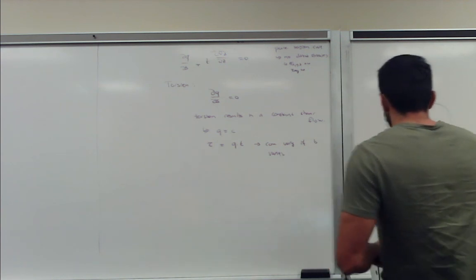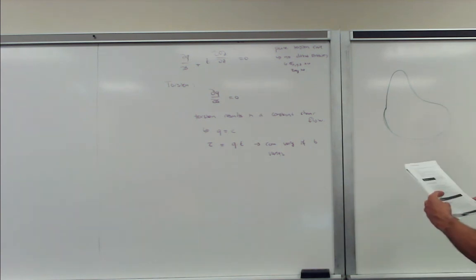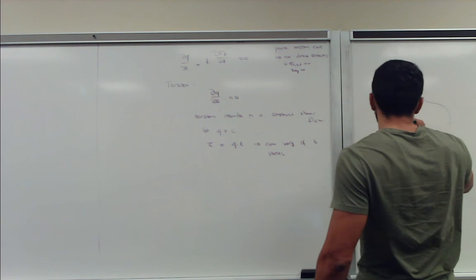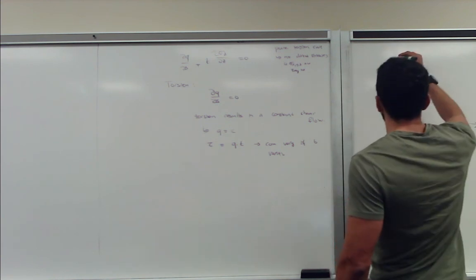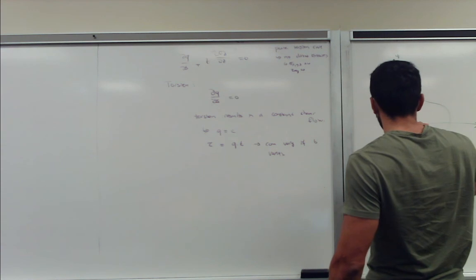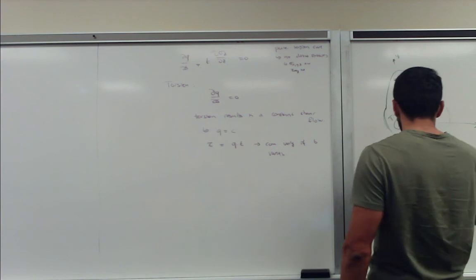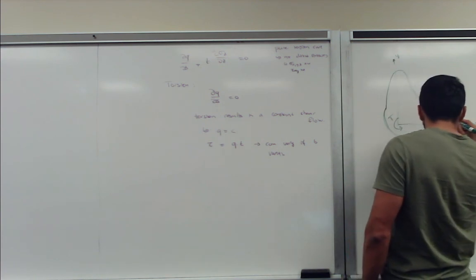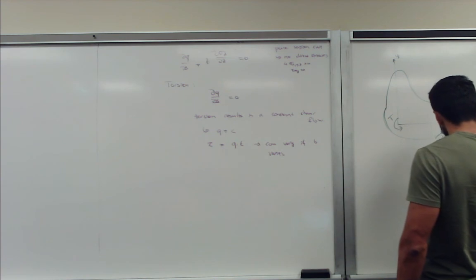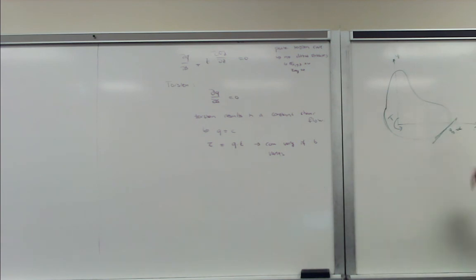Okay. So we have our x-axis and y-axis, x, y. Torsion is applied somewhere. And we know that on any segment in our cross section, let's take this segment, the shear flow will be a constant. So the shear flow q_s, that will be a constant c. And then of course, what we have to do is we can relate the shear flow to the torque